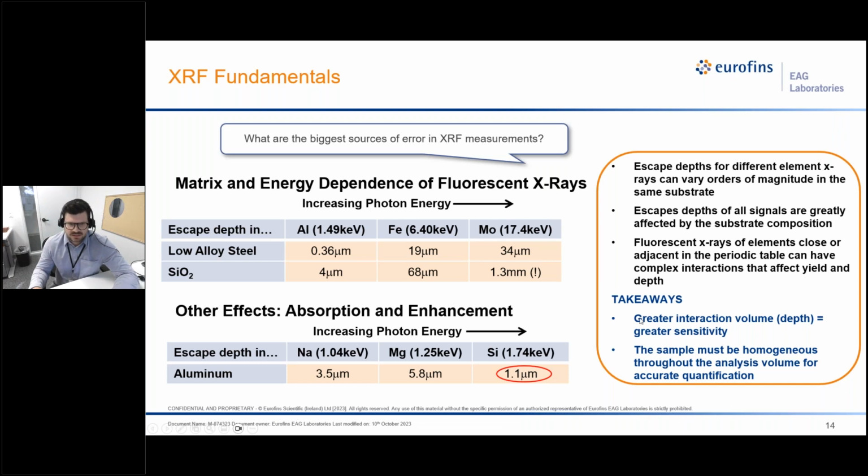All right, some takeaways then to bring home with you are the fact that the greater interaction volume or depth we are analyzing from a sample will directly correlate with greater sensitivity. Also, the sample should be homogeneous throughout the analysis volume for XRF to get accurate quantification.